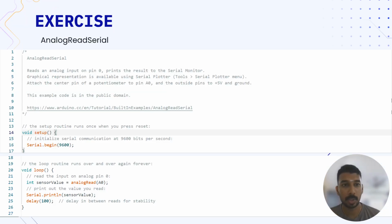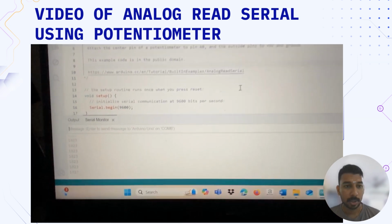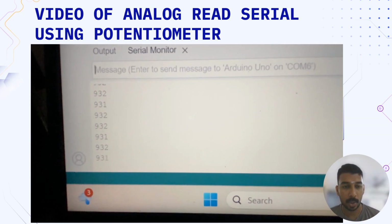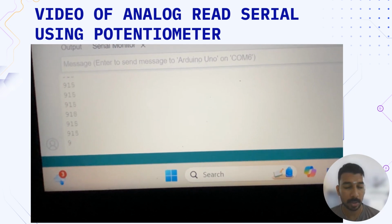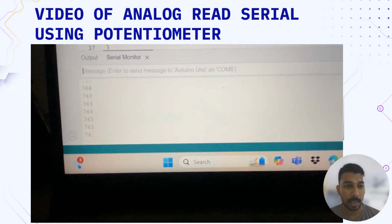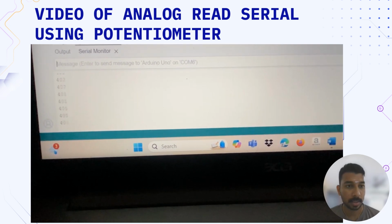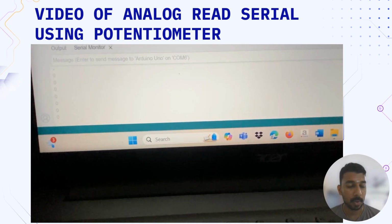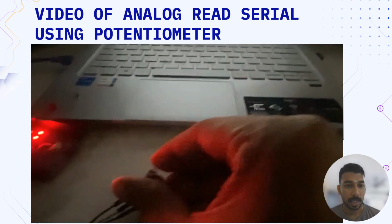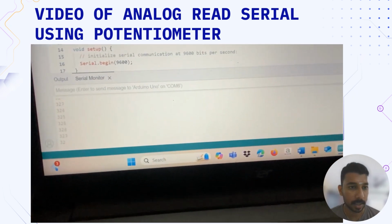So the first exercise is to use analog read serial. So once we upload this data, the video of the analog read serial is here. The value will be ranging from 0 to 1023. Now the value is showing 1023, and when we turn the potentiometer to the other end, it will slowly reduce to a value of 0. So now the value is indicating 0 on the serial monitor. Then when we turn to the other end, it will again show 1023.